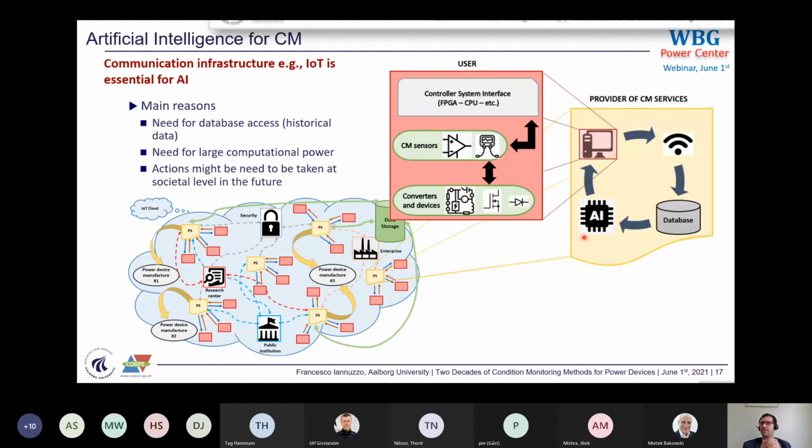And this is definitely one good point. You can play with the cooling system, definitely, no doubt, and I would say in the other direction. You can save cooling power, for example the fan speed, which also takes some power, reducing the overall efficiency. If you are aware of the junction temperature, and it is not too high, then you can reduce the fan speed or even turn it off in principle. So you can do something like this, definitely.